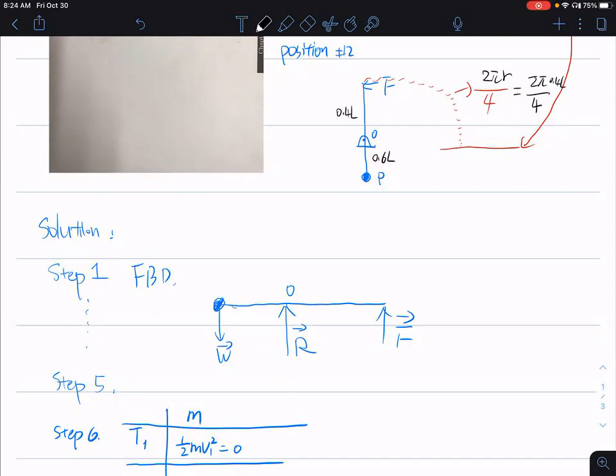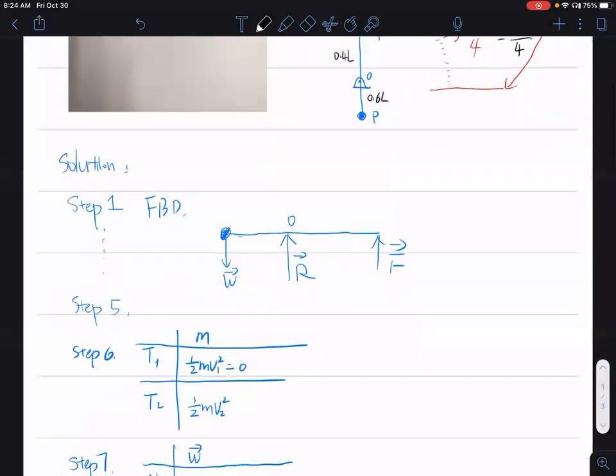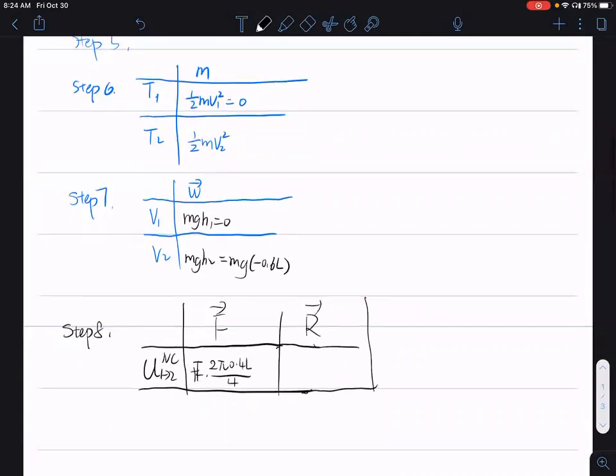I think it's 0. Why is it 0? Because the force applied by that is just keeping it from translating. Like it's not moving. Not moving. Yeah, the equation to calculate work is force times distance. Any distance point O travels under that force? No, right? It's a fixed point. So here it's just R times 0 distance.